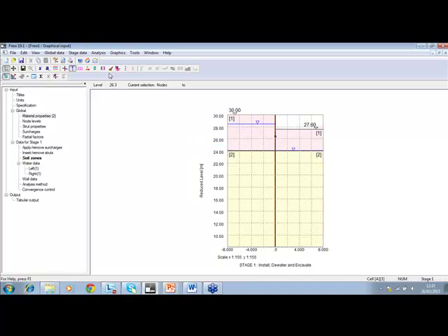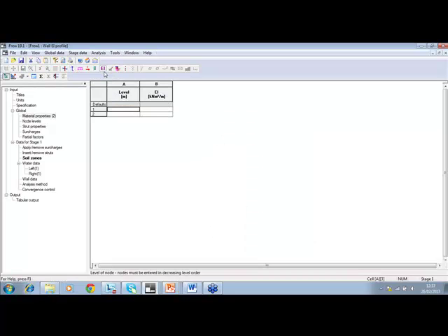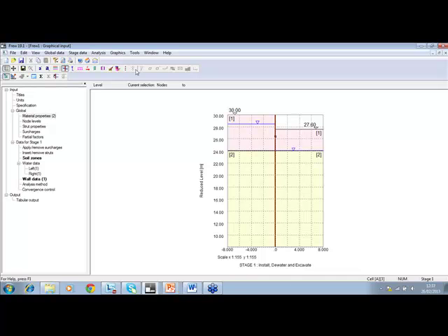And I am going to add stiffness because the wall has been installed, so it needs some level of stiffness. I'm going to put this wall at the top ground level, but it can be below that. And the actual stiffness value depends on the type of wall you have. Okay, so contiguous, sheet piled, whatever it is, that would impact on your actual stiffness. Okay, so that's stage one, done.